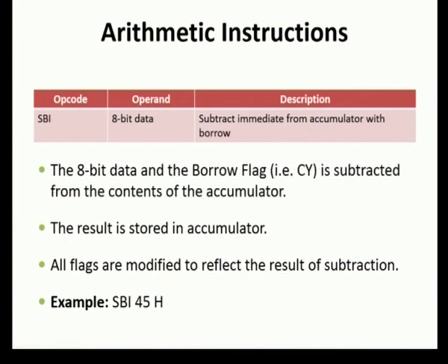Another one is subtract with borrow immediate data, SBI. Immediate with borrow: the given 8-bit data and the borrow flag are subtracted from the content of the accumulator. The result is stored in the accumulator. Flags are modified based on the resultant value.